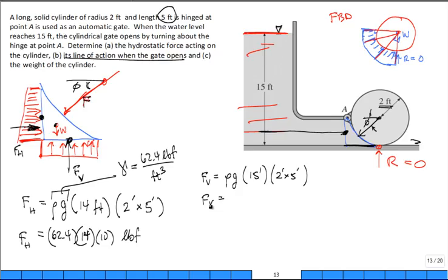All right. Let's do this now. What is the weight of the fluid? What's the weight of the fluid? It's going to be tough. So what I would do is I would say rho g times the volume. And the volume would be this volume subtract that volume. Does that make sense?